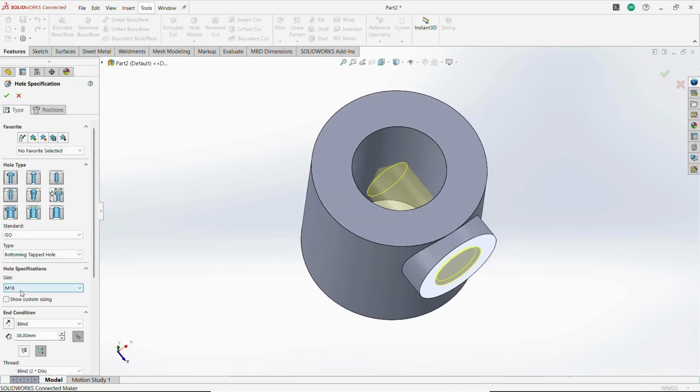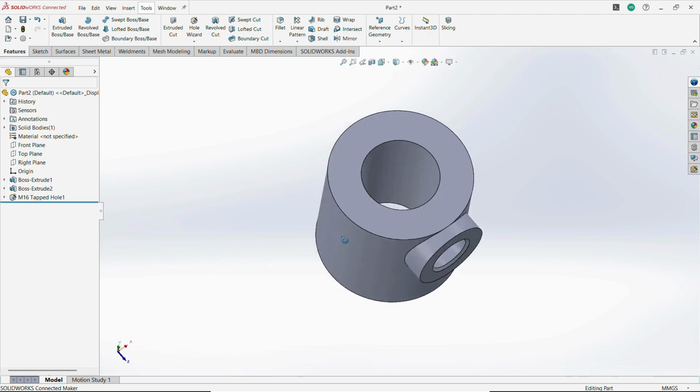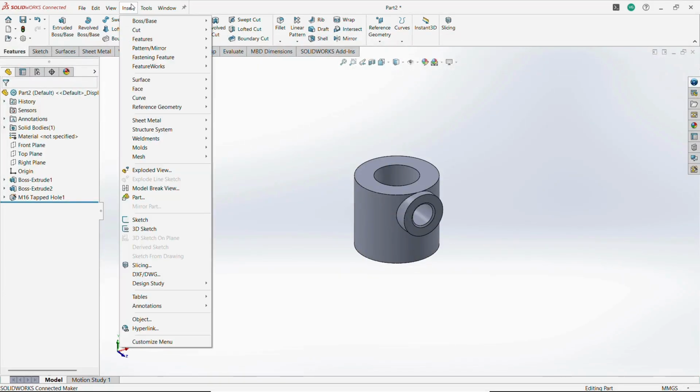Step number 2 and step number 3: that is creating a new solid body by using an extruded boss and using a hole wizard to form a pocket under this distance. Okay, once it is created, now the fourth step is to create a new same kind of body.